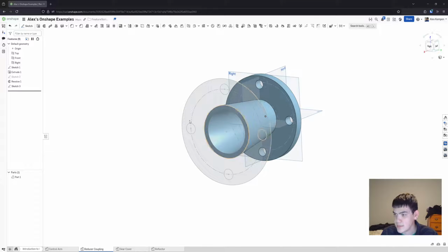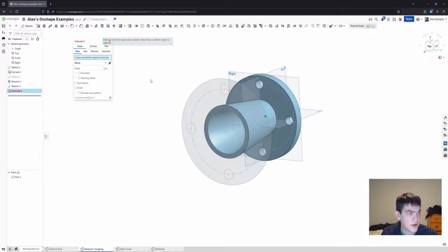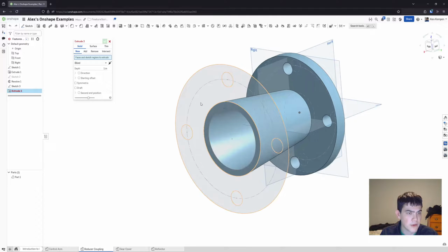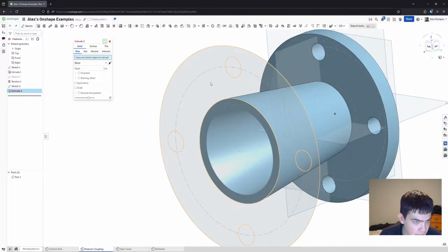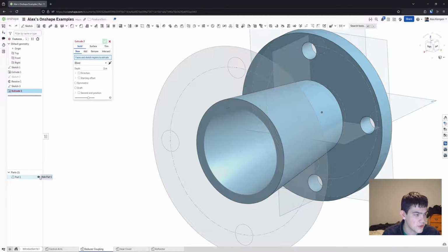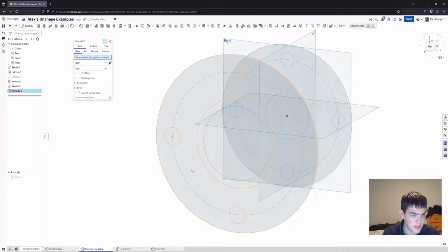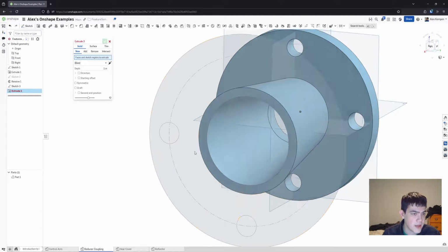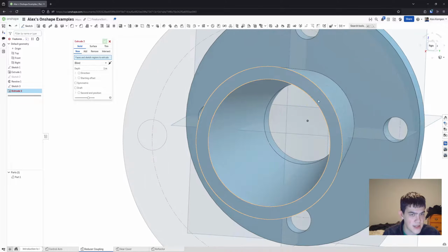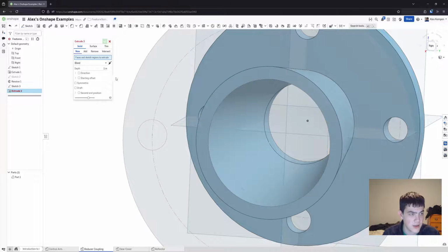And show it. So then I can go ahead and extrude it, right? And so one thing I'll point out is my sketch actually has 2 faces, right? So if we hide this part, you can see visually my sketch should have 1 face here, right? But I actually get 2, right? And the reason for that is because we're actually imprinting on this face because we're sketching on it, right?